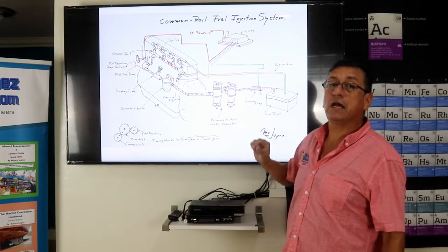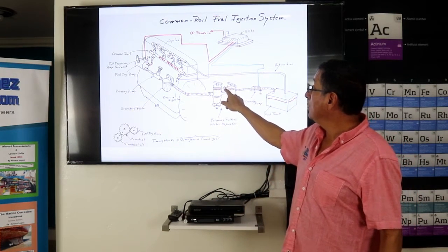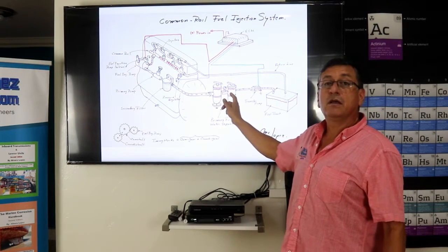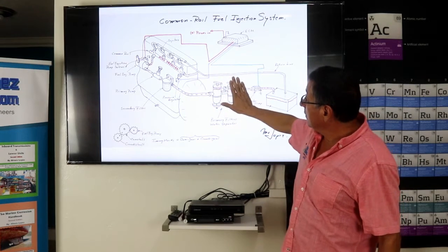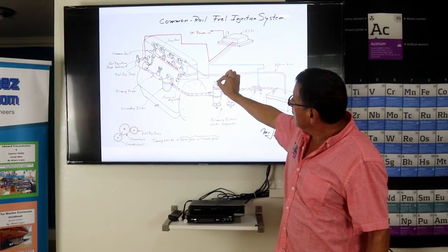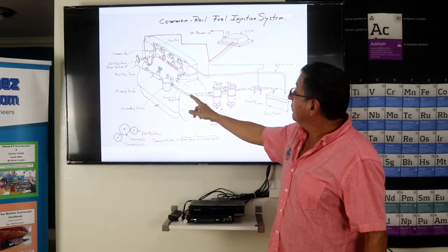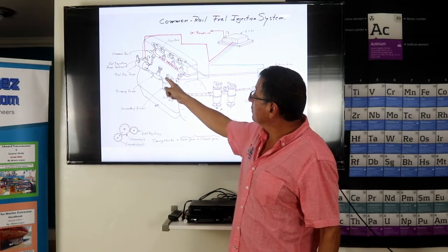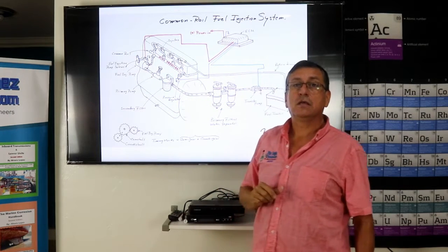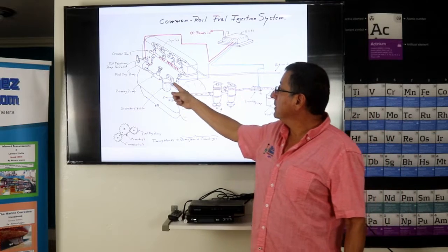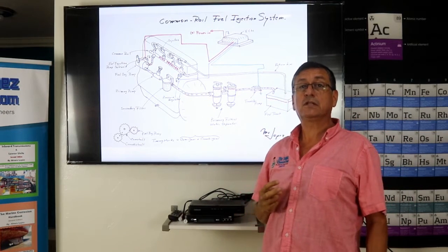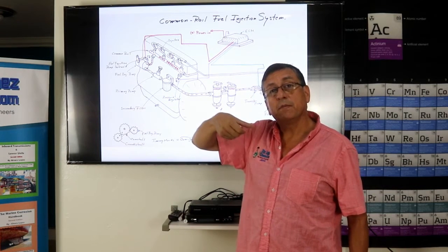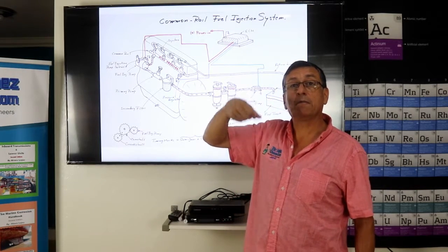This is very important. I explained in a previous episode how to read the pressure on the pressure gauge located in between both filters. In some cases, if you only have one filter, you have the pressure gauge on the handle, on top. After that, we have the secondary filter. Normally the secondary filter is bolted on the block of the engine, it is part of the engine. The secondary filter in some cases is a tandem, two filters, and it has a bracket where you can bleed the system and where you can prime the system.